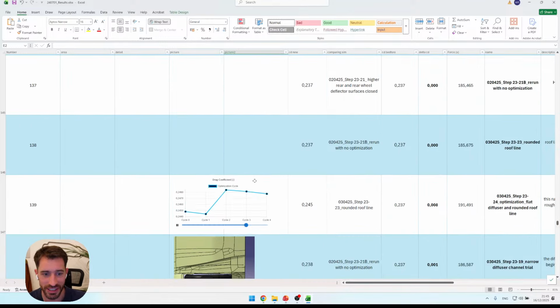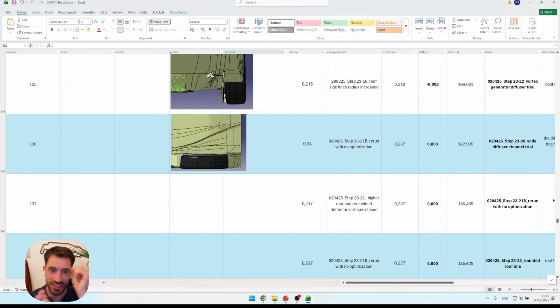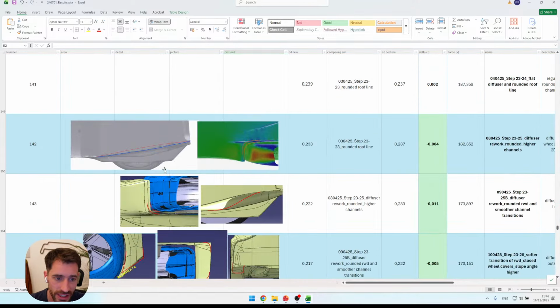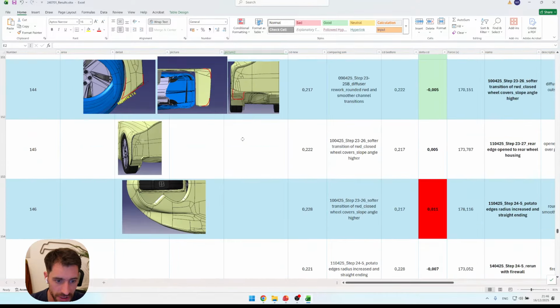So this one continues. We worked with vortex generators to energize the airflow before it enters the diffuser to maintain attachment. This is a special diffuser channel which actually was a bit deeper because the chassis was a trapezoid shape, and then this channel would sit right in between that existing chassis. So it very much was an exercise of optimizing within existing constraints, different geometries for the diffuser.